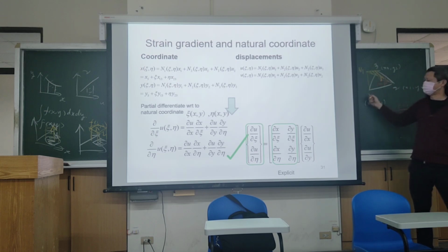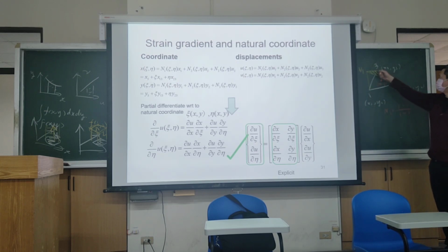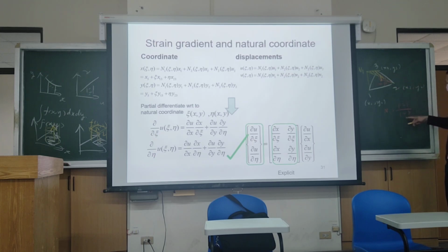Shape function is 1 at point 1, but 0 at the opposite end. But if now I have an arbitrary point, I want to find the shape function. Of course, I can go back and do the calculation using complex variables, but the easiest and simplest visualization is the isoline through that point, which should have the value of the opposite small sub-triangle divided by the whole triangle.